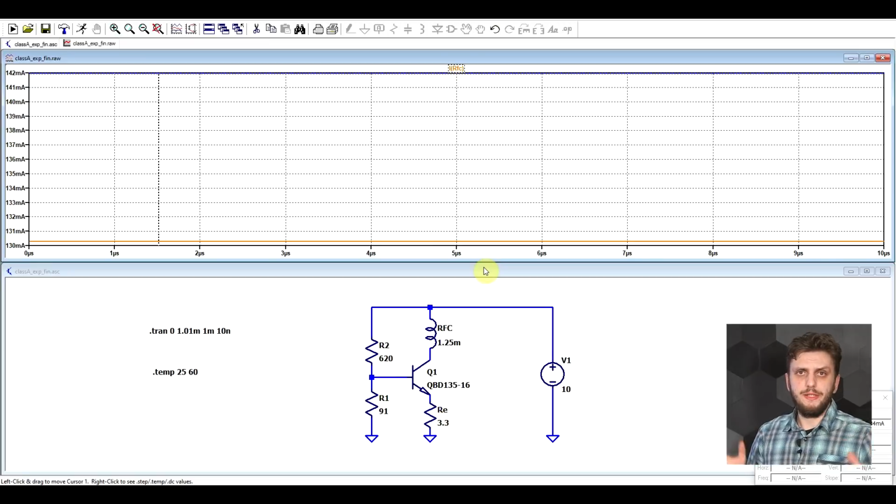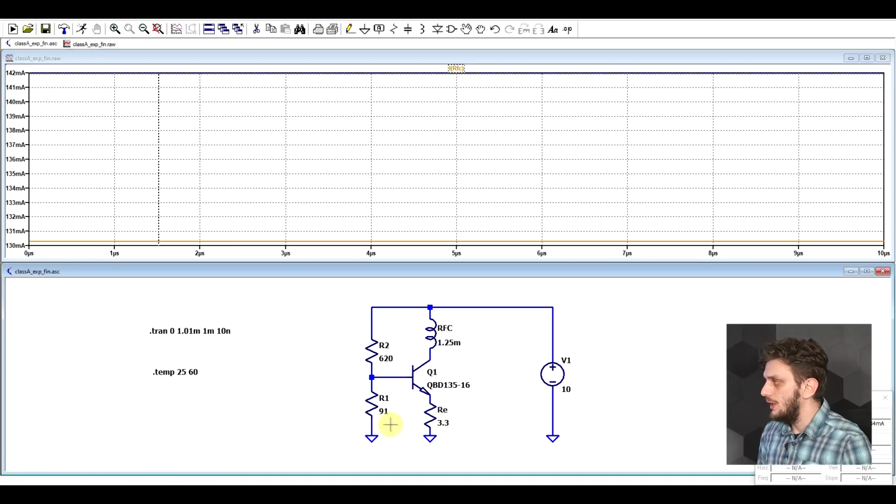Now, other than waiting for the transistor to heat up, another thing that we could do is increase the value of R1, but for the moment I'll leave things as they are. So the higher the current at which the transistor is running, the lower the gain it will have. So that's why I'm leaving the circuit as it is.